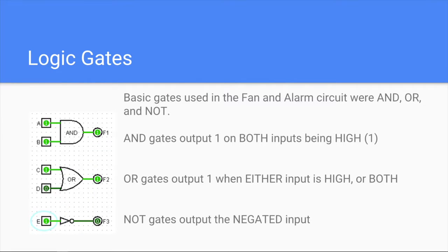The truth tables gave us the following gates to work with: 3 AND gates, 1 OR gate, and 2 NOT gates. We can easily read this straight from the equation, when it reads, on the alarm, V and T'. The AND gate is inherently said as you say it out loud. For the fan, C and T, or T and V'. Hence, 2 NOT gates, 3 AND gates, and an OR gate. Here we can plainly see the use of AND, OR, and NOT applied.